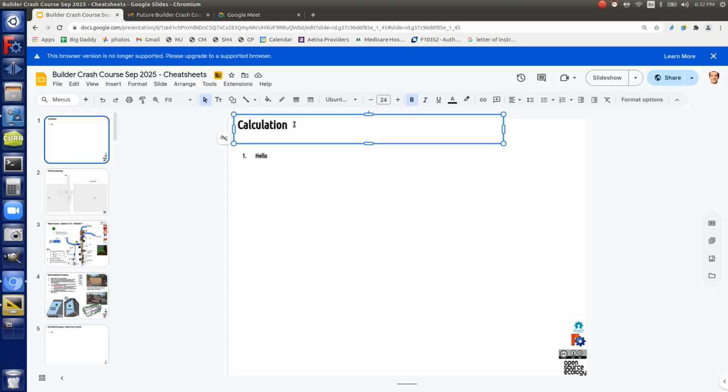If you took the same amount of wood but expanded it, say you get a box of 2x10, 2x10, 2x10, 2x10, with the same amount of material as a 6x6, which it's probably close to, then the bending issues are much less. So the 6x6 might start buckling, as in bending.